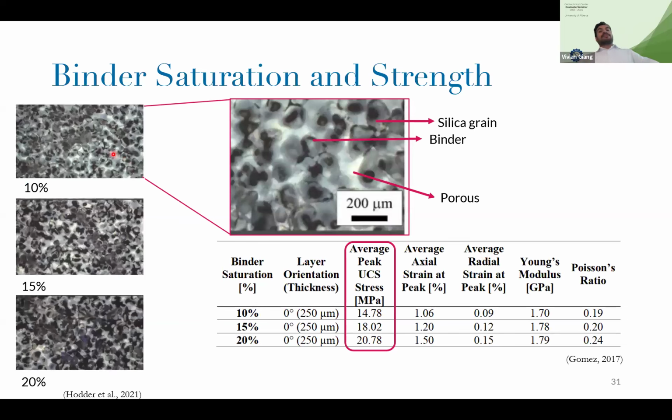How? You remember that during the printing, the head of the printer was applying a chemical. That chemical is called a binder, which means the link between one grain and the other grain. So if you reduce that percentage, what you have is a softer material. So for you just to realize that, I took 2 samples. You can touch them. The big one, if you try to take grains from the big one, it's tough. If you try from the little one, every grain is right there.